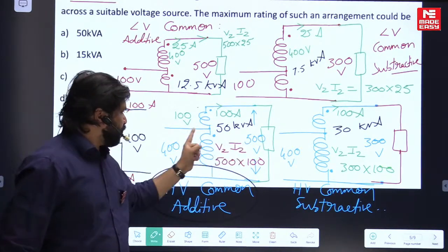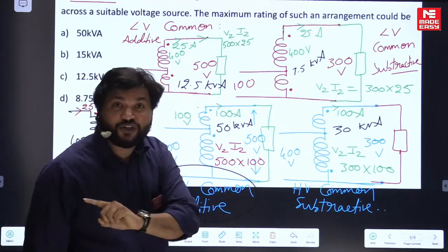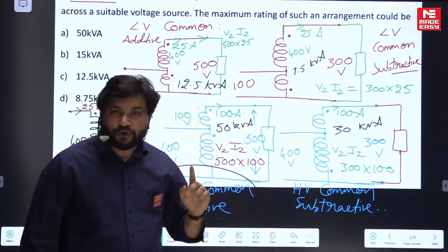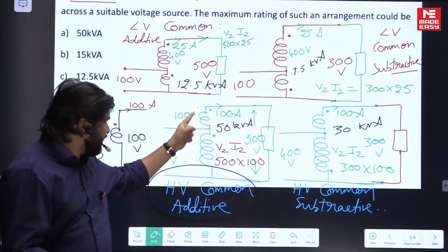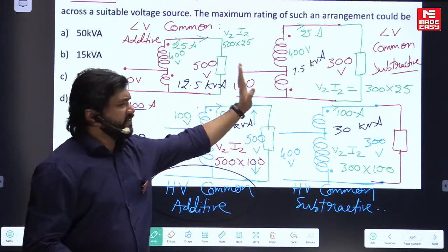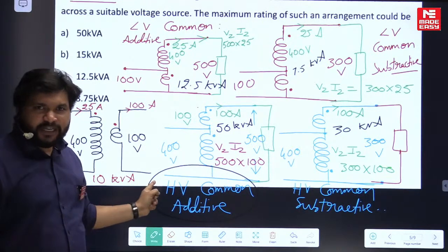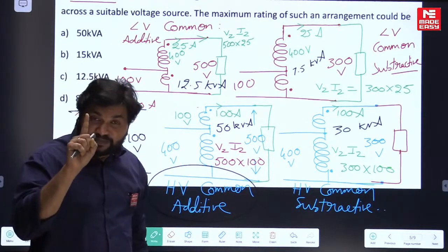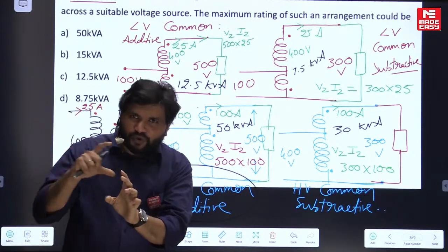These are voltage ratios: input voltage, output voltage. Voltage rating across the winding doesn't change. I'm talking about voltage ratios like input voltage, output voltage, because you're connecting the relative polarities. Definitely secondary, like across the load, voltages will vary. Across the source, voltage will be there, but across the windings, voltages must be the same. 400 volt winding, across the 400 volt winding, 400 volt only.